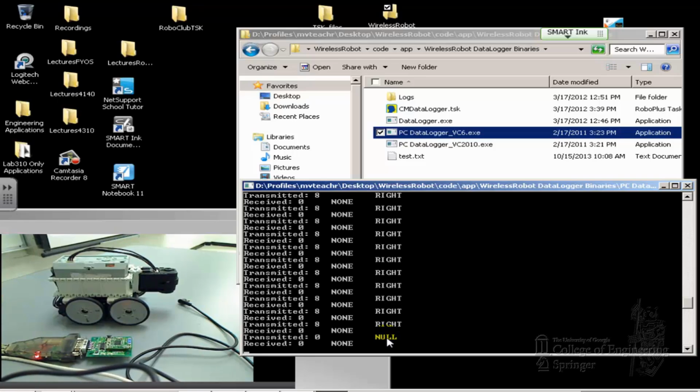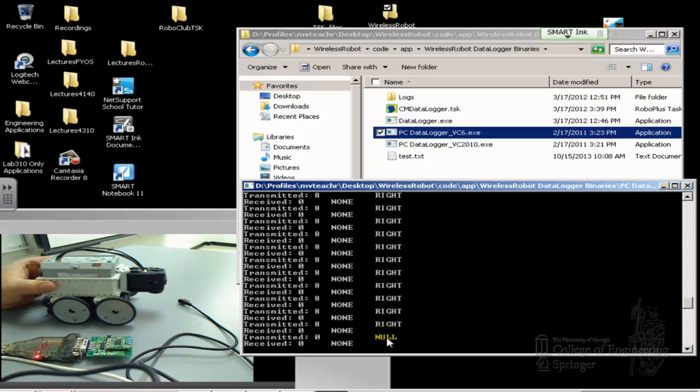When you read the code, you're going to see that we can also send special packages, and you can send different numbers. Basically, a message is just a bunch of numbers. So you can use WASD essentially to simulate the RC100. And you can see that in the main program, I can build in, so if I push the number 1, 2, 3 up on the top row, it should be able to understand that. It's not in there now, but you can do that. Let's see if I do it or not. Oh, it did do that. Okay, so buttons.